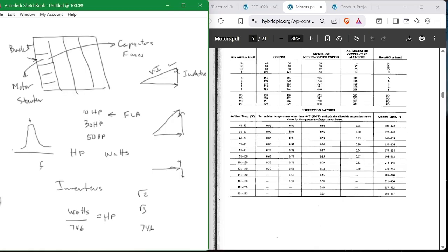So basically, if you minimize this and minimize these, you get that. You don't have to understand a lot to understand that you can pick off one frequency at the expense of all others. If you minimize the X sub L, the X sub C, and the R, you get a high peak. And that's the intermediate step that most radios do somewhere or another.